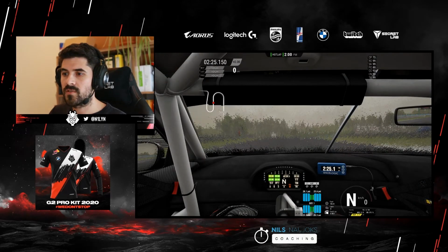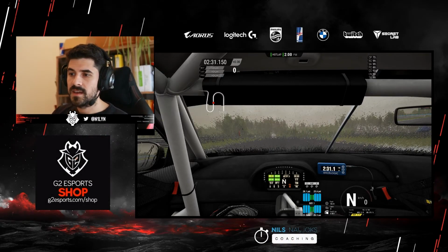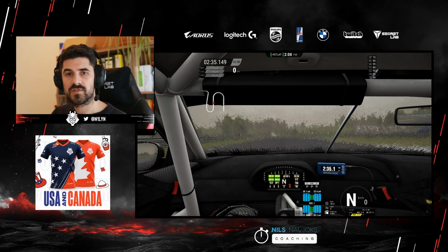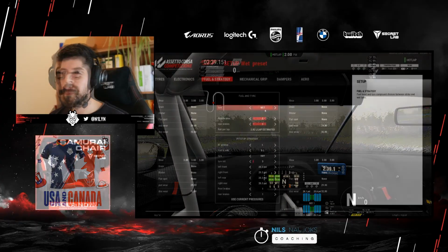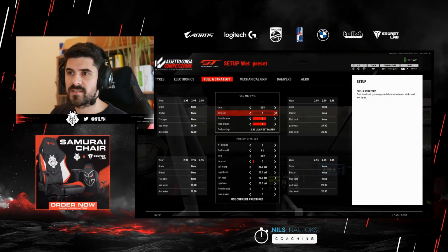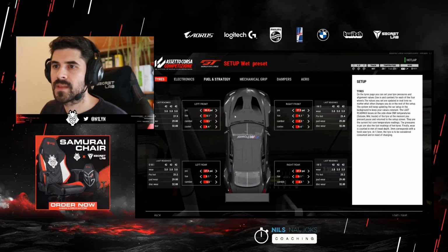So if we take it to the track now, you can see the tire is colder, and I've set up 30 psi on the front left. On track, when it starts cooling off, the pressure is actually going to decrease and comes back to the window. Now, back in the pits, let's go for the wet tire. And I really only want to walk you through the line of thinking there and not really do too long of a video for you.